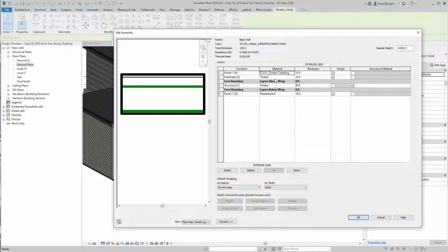It's more your finishes palettes that are tagged. But it's up to you. If you want to give your normal structural materials a coding system, it would be smart, but it's not compulsory. Same with plaster. In fact, plasterboard, sometimes it does, but mostly you are tagging the finishes on the plasterboard, i.e. a wallpaper or a timber cladding or, I don't know, a white paint. You don't normally schedule out the plasterboard itself.